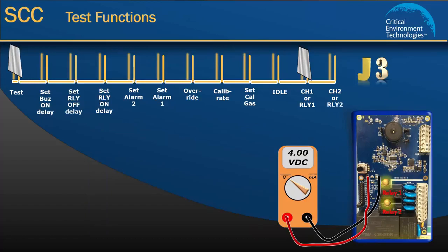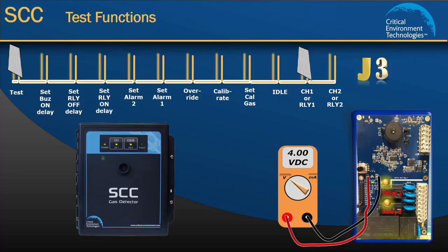Watch the LED lights on the front of the enclosure as they cycle their test functions and make sure they all turn on and channel 1 and channel 2 show both green and red lights. To test relay 1, turn the rotary encoder dial clockwise slowly until relay 1 produces an audible click. The test points will output 3 volts and the relay 1 LED light on the board will turn off.